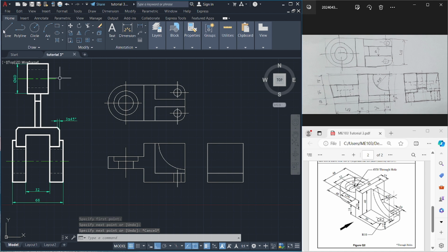Again, I have to locate the center point so that I can offset the same by 10 in either side. Or this way, offset this one by 5 in order to get the 10. Sorry, so this offsetting by 5 on this side, and also another 5 on this side in order to get this thickness of 10 here. So this line is no longer useful. I know this should be going to this point, and I can just draw this way and trim.